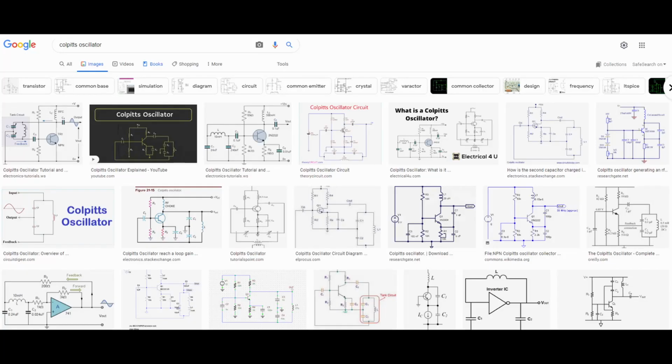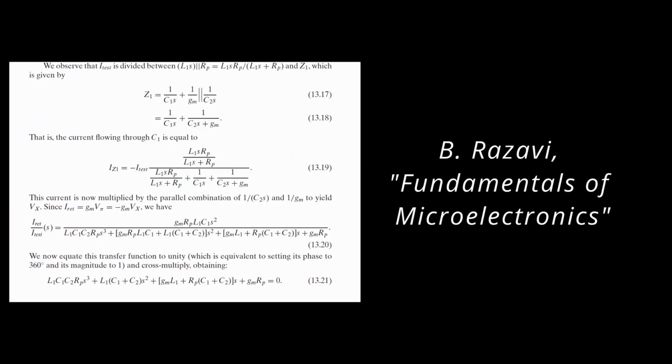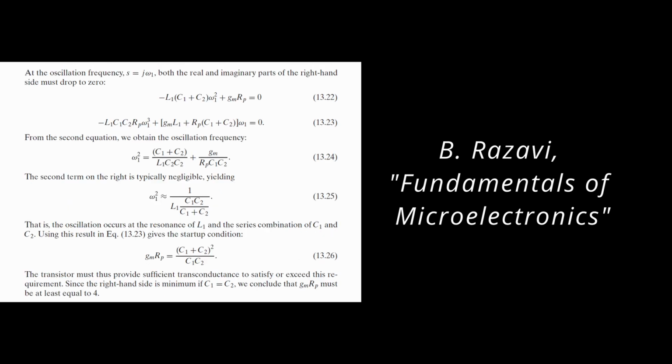I'm going to use a Colpitts oscillator because it works well with constant signals within the frequency range that I'm looking for, which is pretty much anywhere around 200 kilohertz or so. Now I'm a little out of my depth when it comes to oscillator design. It's super different from anything I've ever had to do yet, and seems to rely on some pretty complex stuff.